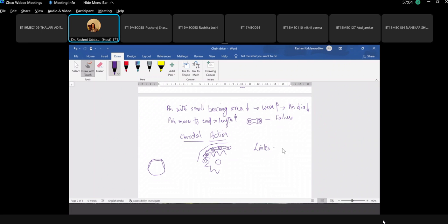And it's because of this movement of the chord that when it comes here, it has to change the angle, the relative angle between these two, till the time it leaves the sprocket and becomes a straight line. Again, while it goes through the sprocket, it has to bend and its angle is changing. While the angle is changing, it will rub against each other because it's metal. So the two link plates rub each other and that creates a lot of noise.